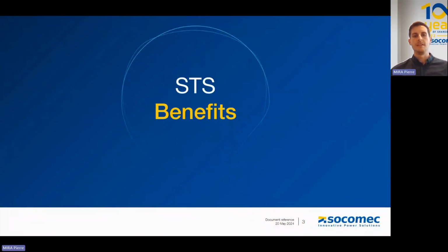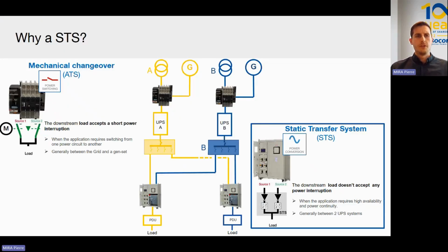So to begin this webinar, we want to speak about the STS benefits. So how does STS improve your data center architecture? To speak about this topic, let's introduce the question, why a STS in an installation? So first, the difference between an ATS, automatic transfer switch, and an STS, static transfer switch.